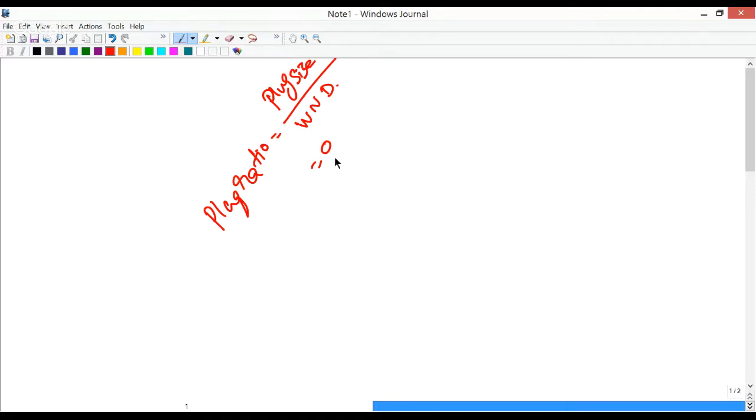So assignment 2, question number 9. When the ultimate tensile strength of the steel increases, failure of resistance spot weld will. So obviously high strength material means you also have higher alloying elements, more carbon, right? So then the failure mode changes from full plug to interface failure. Okay.